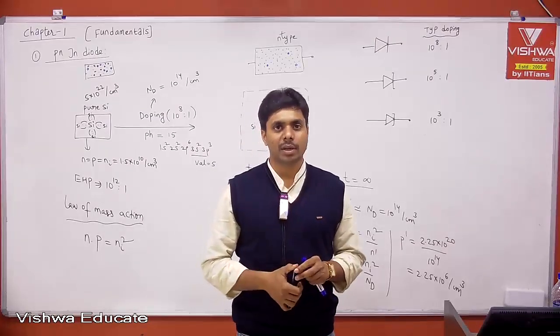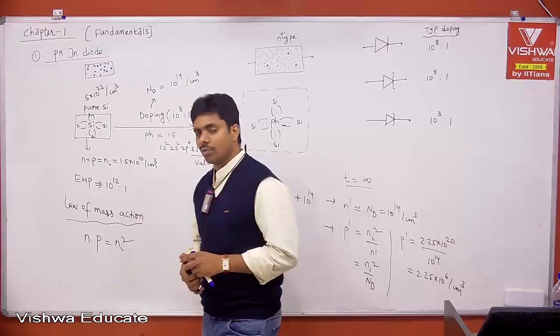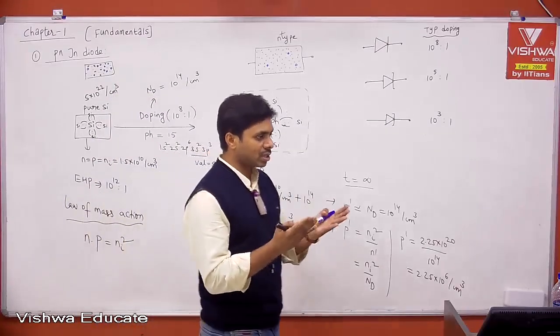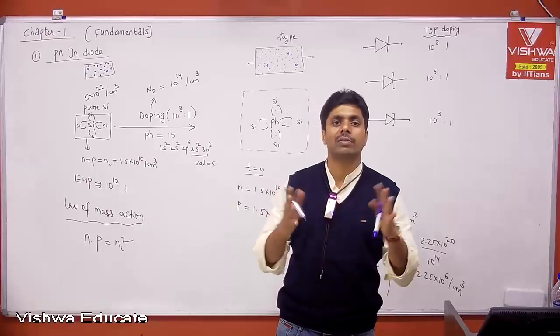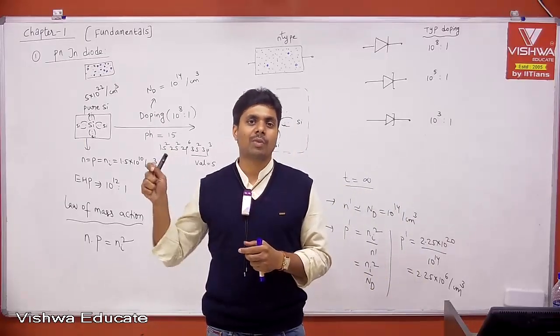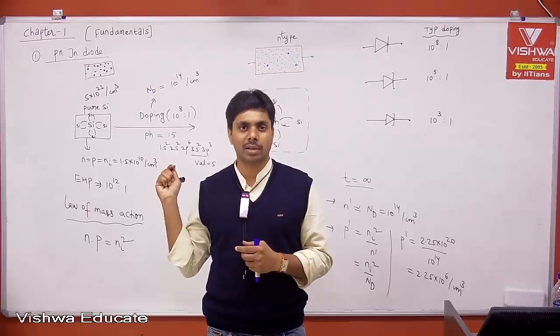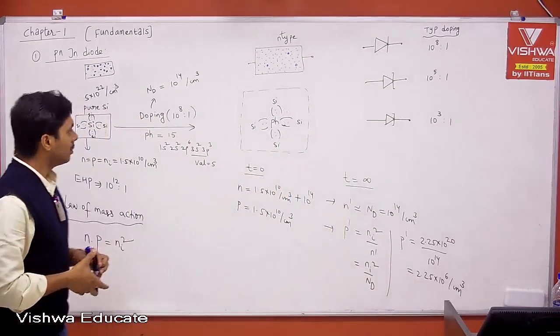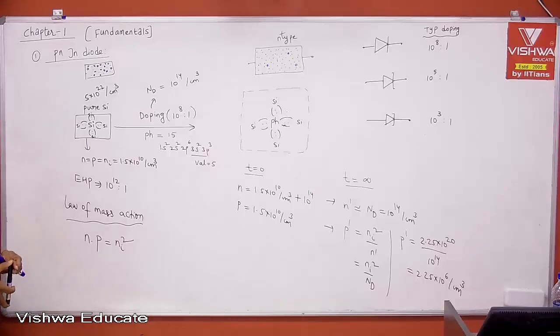I can stop here because I wanted to explain what V0 and V gamma are, and because in the BJT we'll have two PN junctions, with two different V gammas or two different V0. That is depending on doping, and that is what I explained. Okay, done. Then I'll go to the PN junction diode VI characteristics.